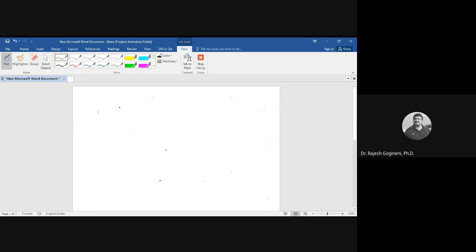So I will tell you the nodal. So put the heading, write down nodal analysis. Already we have discussed when nodal analysis is applied and when mesh analysis is applied in solving circuits. If the circuit has a larger number of voltage sources and you want to find the mesh currents, we will use mesh analysis. And if the circuit consists of more current sources and you want to find the node voltages, then we will use nodal analysis, right?